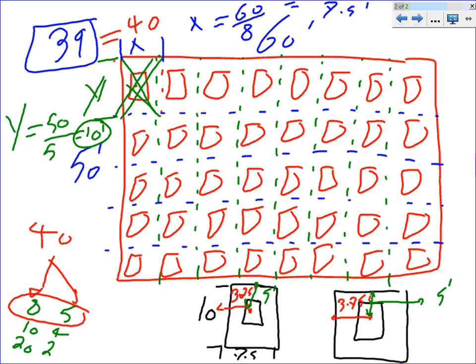Now from there, if I find the center of the first fixture, I can add the distance from here to here and from here to here, which we know, and then you find the center of the second fixture. The same distance applies for this row. All you have to add is now we have a 5 here. We have 7.5 plus 3.75. That will get you the center of the second, and you keep going to the third and the fourth and the fifth. Any questions, guys, about finding the center of the first fixture?